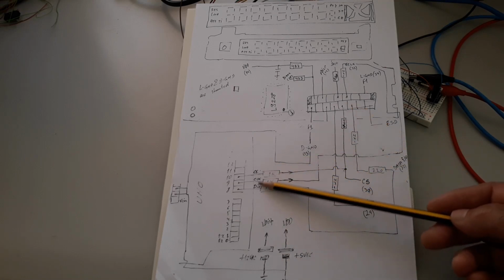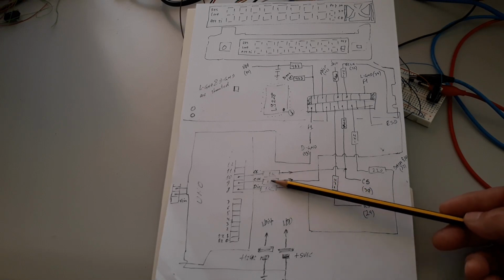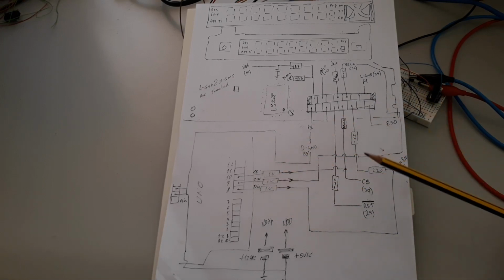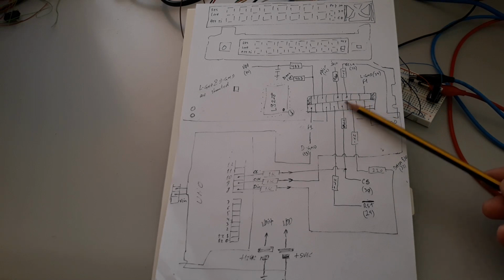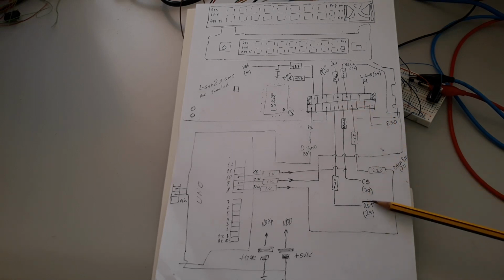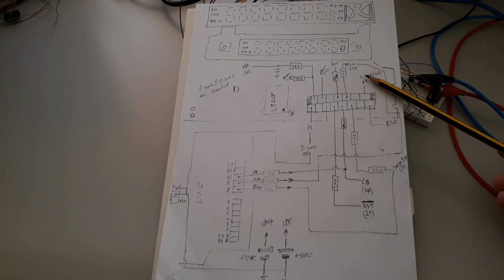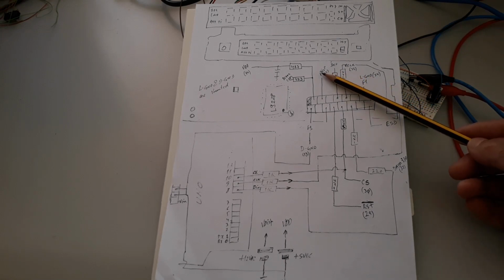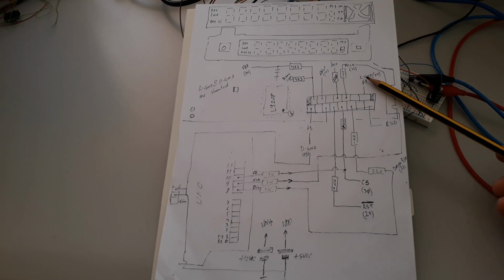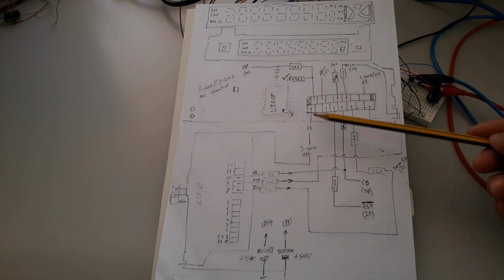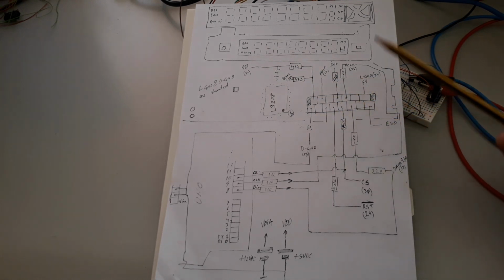I use 1K resistors to protect, but it's not necessary. The pins coming from the block have the same names. The reset is internally connected to the VCC, it is not necessary to force it. The GND from the voltage to the segments is shared or is connected internally to the logical GND, and that's all.